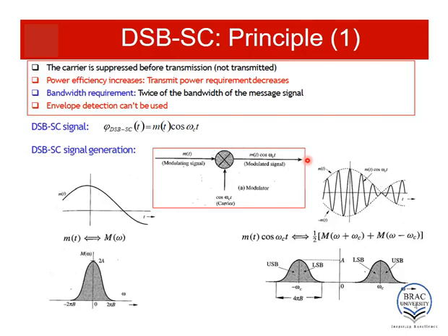As you can remember from the previous discussion on DSB-C, there were three steps of drawing a DSB-C signal. In the case of DSB-SC, the first step is not required. What you will need to do is draw the message signal, draw the reflection of the message signal, and the last step is to insert the high frequency carrier in between. Straightforward. Okay, now let's analyze it in the frequency domain.